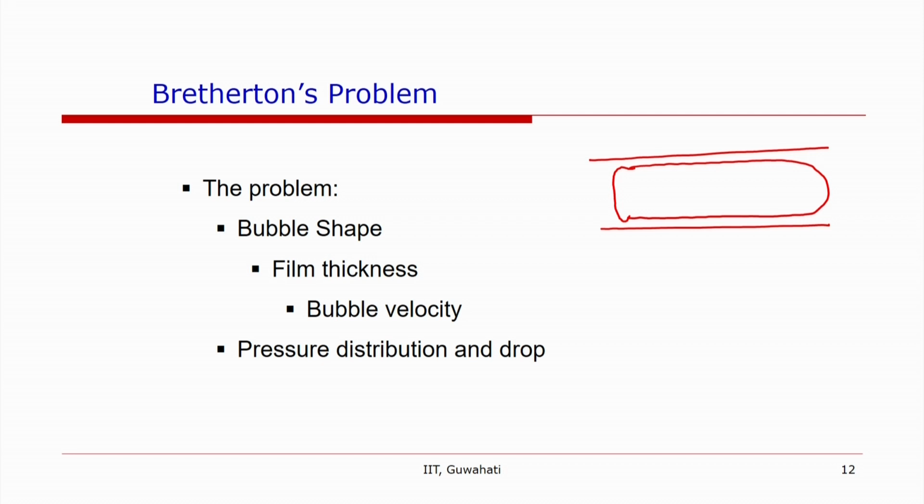Using a lubrication approximation, he analyzed the flow behavior around the bubble and used the Young-Laplace equation for the pressure jump across the two phases near the interface.